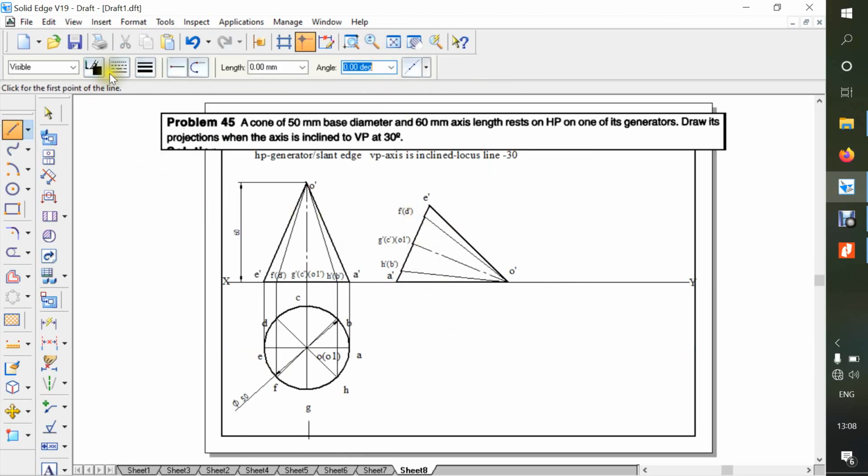So now we need to go with the projections. So first, as we know, the right extreme one, O. So O is here. So click to the O. So next it's E. So E is on this point. Okay, so next is F and D. So D is here. So press tab and 90 degree, you will get clearly. So one is D and one is E.